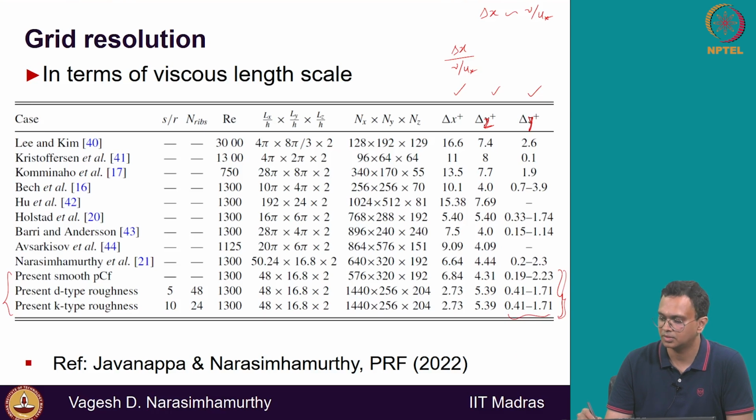0.41. So this is the y plus, the first grid is set at 0.41, right? I have told you to put y plus 1 at least, right, in RANS when you use a low Reynolds number formulation. Here I'm having more grids there because I need to compute the gradients also there for the wall shear stress, right? So I'm having more points so that my wall shear stress data is better. I need to compute du dy on the first grid point.